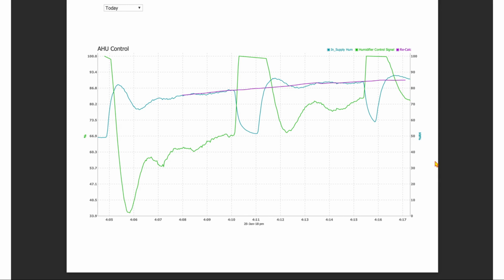So when we say proportional, what we mean is that if we've got a set point, and we'll keep the numbers quite simple, so we want to achieve 21 degrees Celsius, the temperature is below that by whatever units. The proportional setting, if we set it to 25%, that means for every degree of error, so every degree we're below set point, we get a 25% output. So 1 degree below, 25, 2 would be 50. At 4 degrees below set point, we get 100% output on the loop.